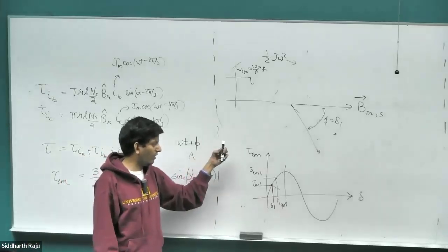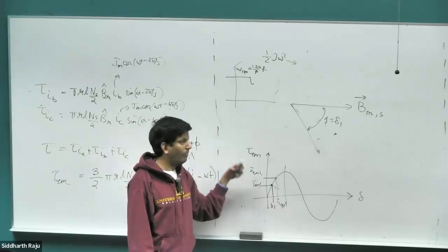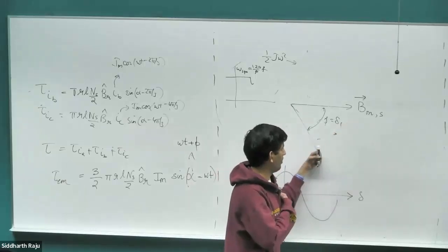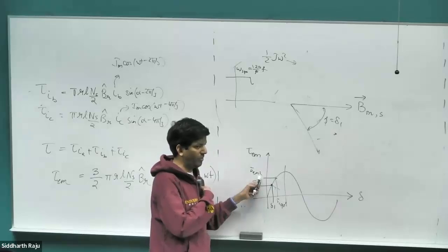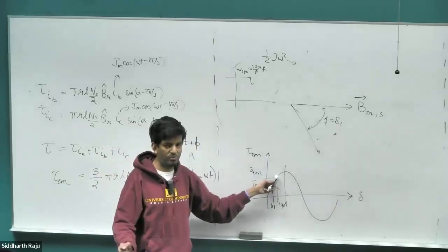You increase the load torque; the motor can reach steady state only if the load torque reaches the same as the electromagnetic torque. When you increase the load torque, the speed came down, and the separation between the stator and the rotor magnetic field increased because the load angle increased. The increased load angle then creates more electromagnetic torque, which can now match the added load torque, and then the motor can now rotate at a stable speed.